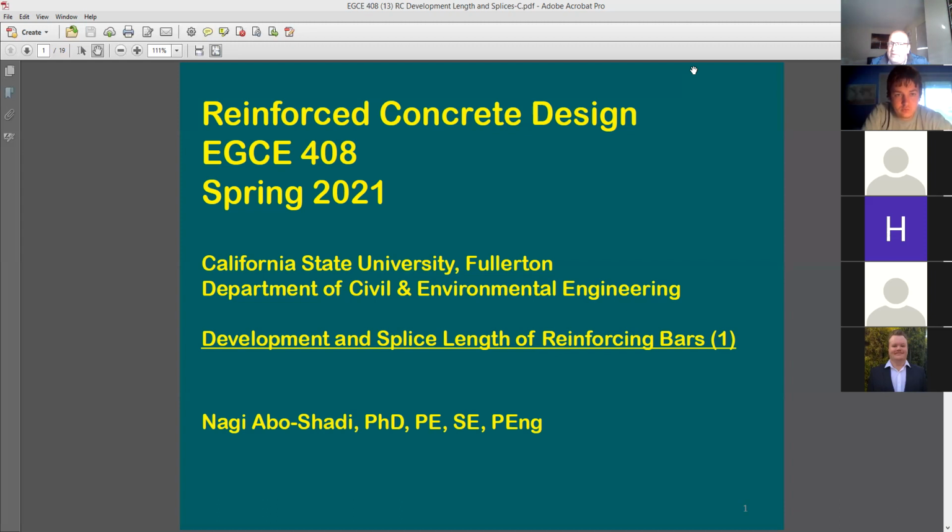And is the footing going to be rectangular in shape or square in shape? Does it say somewhere it's going to be square or rectangle, or what does it say? Square footing. Square. Okay, good. All right. And then after you find out the reinforcing, you're going to do a one-way shear check and then a punching shear check.